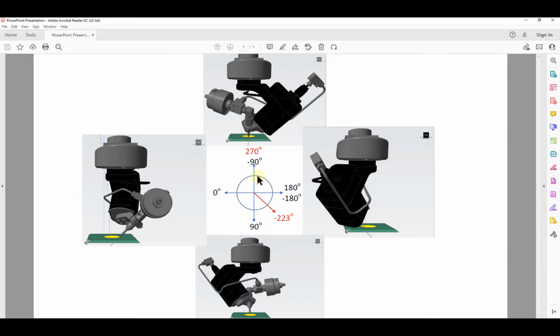If you were doing a top bevel, as shown in this image here, and you put your start point over on the right side for this top bevel on this inside cut, you're pointing at 0 degrees when you start. As you go around that circle this way, you're going to pass through negative 90, and then you're going to hit the negative 223 area, and then the cutting head will do a rewind. The jet will turn off, it'll spin around, come down, re-pierce, and then continue around to get back to 0. So you have a little bit of a blemish there.